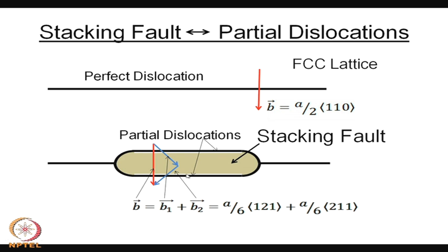But it is possible that this stacking arrangement may not continue throughout the crystal. In some part of the crystal there may be some kind of a mismatch or distortion or deviation from the stacking, and ABC stacking can change over to AB stacking.